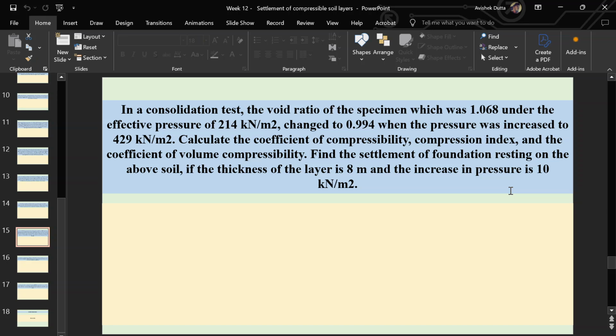Yes, the settlement is very less, but in case of settlement, even in millimeters, it is kind of significant because it is a time dependent process. So whatever we get in the field or in the calculations, it is significant. If the answer is very less, like 10 to the power minus 3 or 10 to the power minus 4, it is of no worries, negligible.